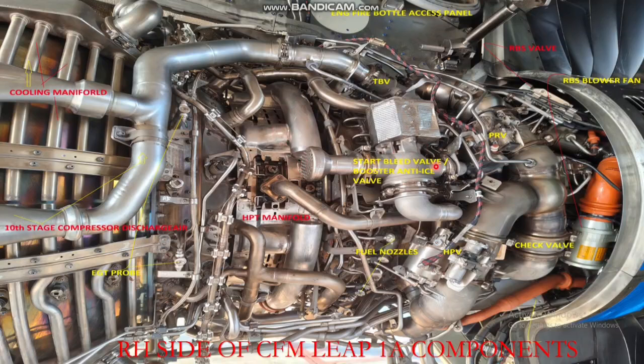This is your start bleed valve and booster anti-ice valve. Regarding this, I have already discussed in another YouTube video. And this is a transient bleed valve, and this is a pressure regulating valve. This is your HP valve. Sometimes people are confused about which one is a PRV and which one is HP. You can check the part number to identify which is PRV and which is HP, but I will tell you a physical way.